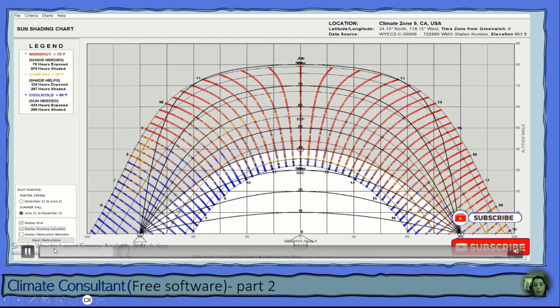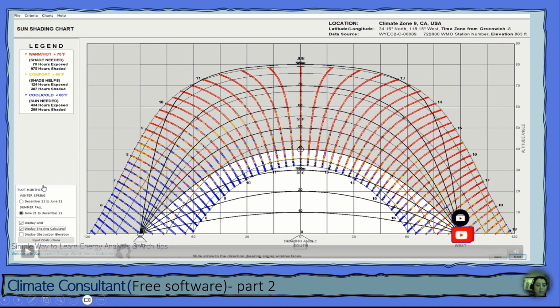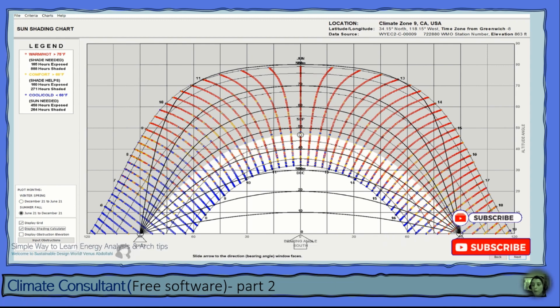So we can use, for example, this 40-degree angle to get a good size for the horizontal shading that we need to apply, to cover most of the bad or extra sunlight that reaches our building. And for these two, as I said, this is for vertical, showing the size of the vertical angle.